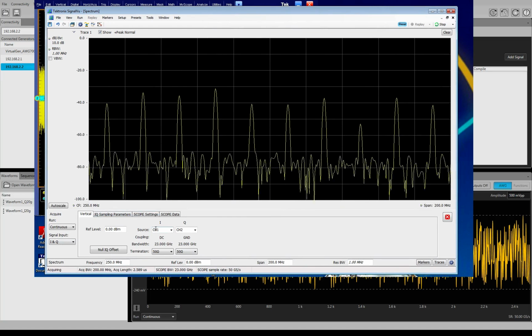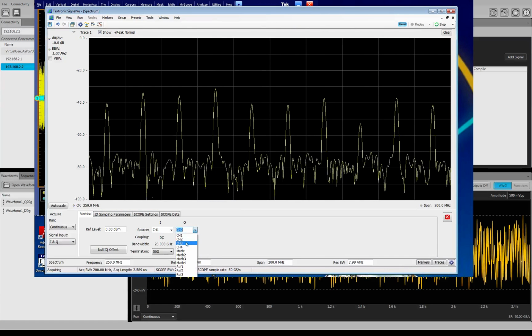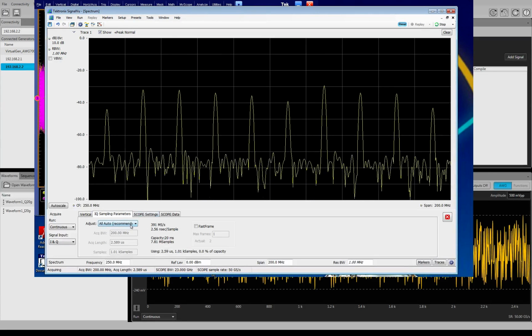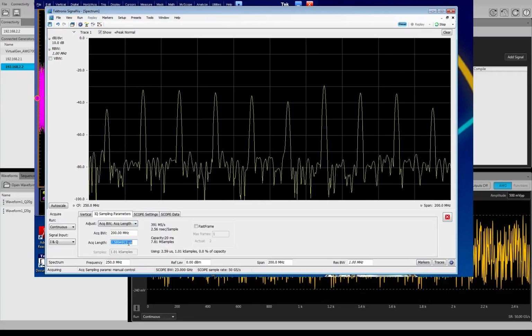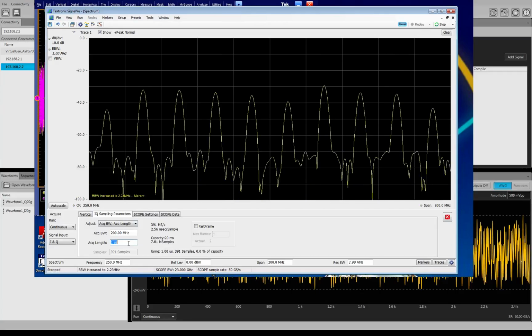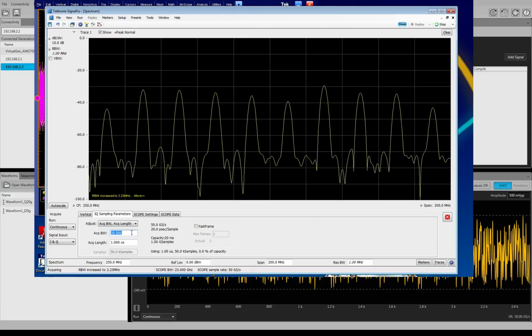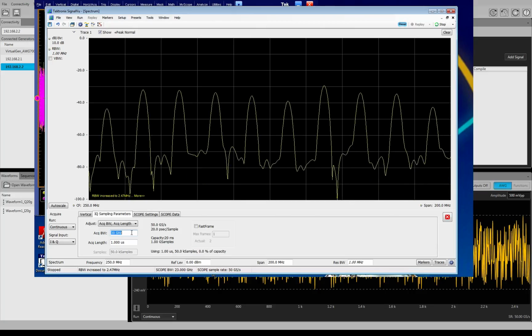We have the source, I is in channel 2, but Q is in channel 3, just to get 100 gigasamples. We have this one. I normally go to acquisition length and put the maximum length to 1 microsecond. And acquisition bandwidth here, maybe 30 GHz or something. Yes, that's it. So as long as you've done this, that's fine.